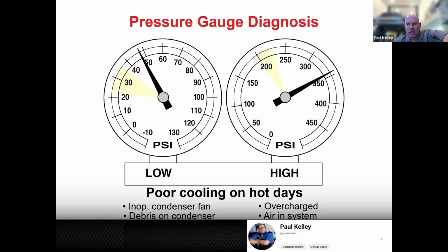So if you have air in the system, a lot of times you'll get these random points where the air has moisture. That's the main issue. The gases that are in the air, atmospheric air, are more erratic with temperature, right? So if it's moisture and it's condensing into liquid, but then it's boiling, that's going to expand, right? That's going to give you a pressure pulse.